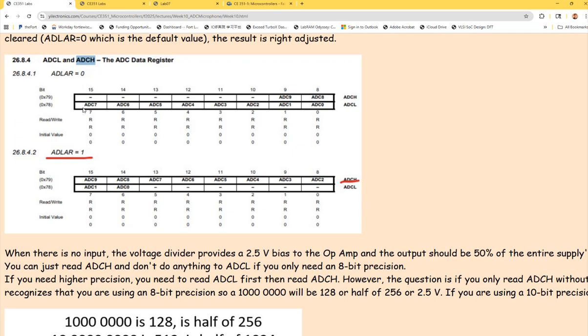Any question on that? We all need to know that. No questions, right? This will be on the quiz or exam in the future because this is such a fundamental technique. In all the other digital chips you have to use in the future, if you got employed by a company and you read the data sheet, if you see the data is more than 8 bits, they will be stored in separate bytes, and you need to do the shifting and OR logic, right? It's really simple and fundamental operation. You just have to know how to do it.